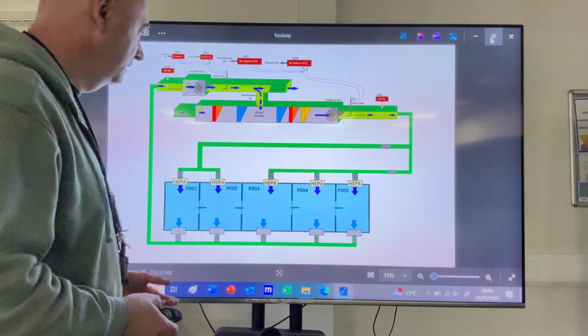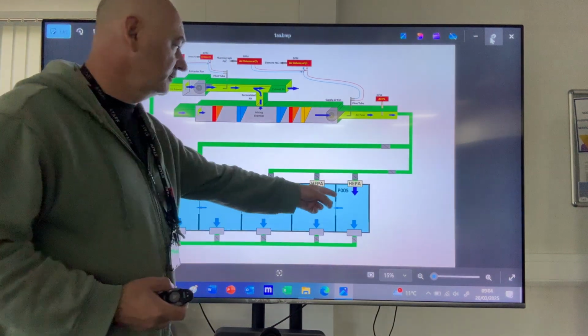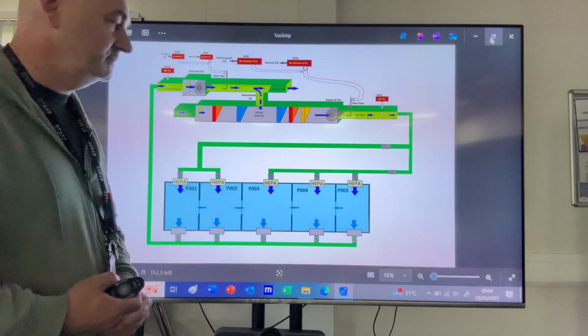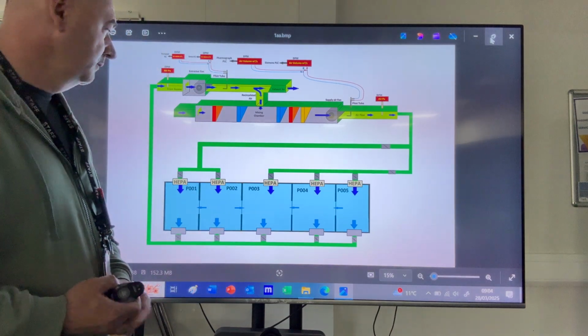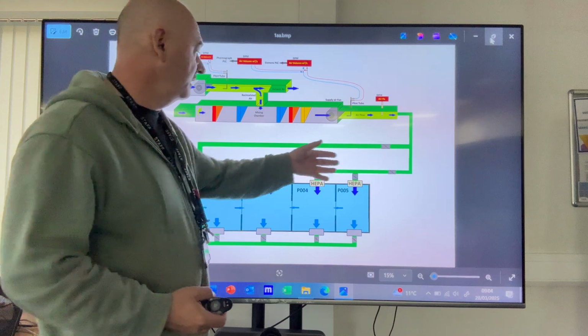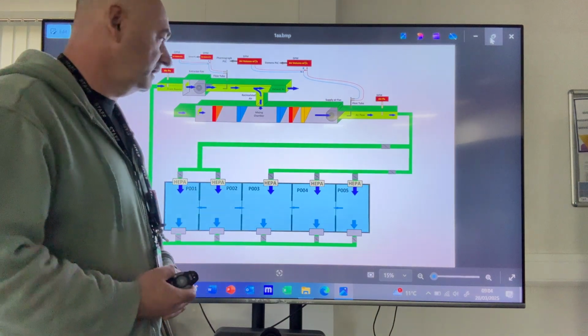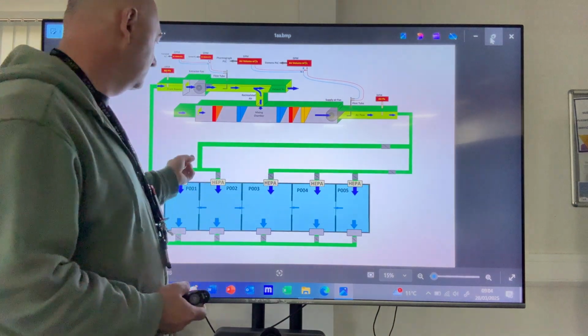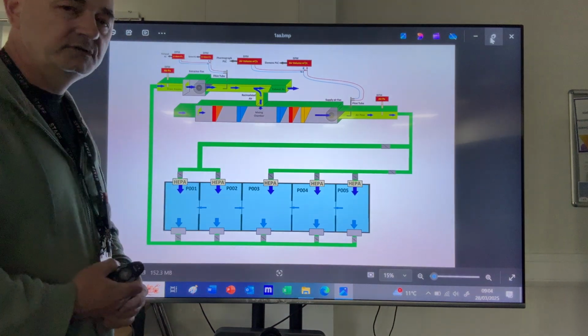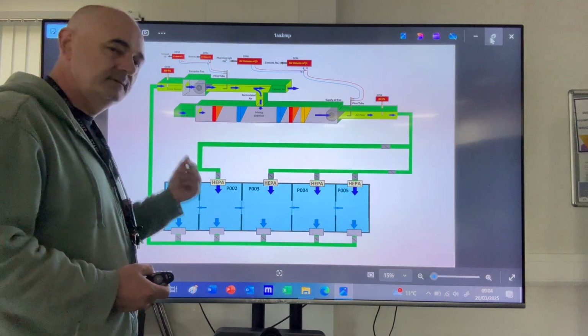the room. If the heat load is not perfectly calculated for these rooms here, we have a problem, because the air has the same temperature in the duct. So on some occasions we have to put extra boosters or reheaters inline in the duct.